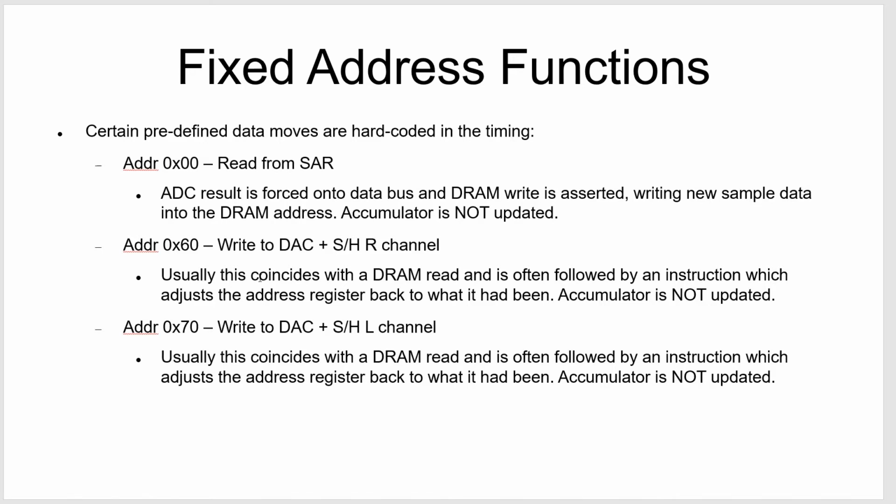When you get to this address, whatever is in the accumulator, boom, it's going to go right out to the right channel DAC. And then you have another 16 addresses here, right? And 16 addresses is 8 instructions. So you have 8 more instructions, and then boom, out goes the left channel.